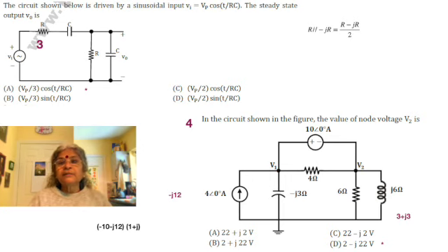When you see 3 plus j3, we try to remove minus j3 from the situation. How? By giving rise to a voltage source. So what's the voltage source? It is equal to minus j12, and the minus j3 comes in series with it. So now we have a total voltage in the circuit given by minus 10 minus j12.